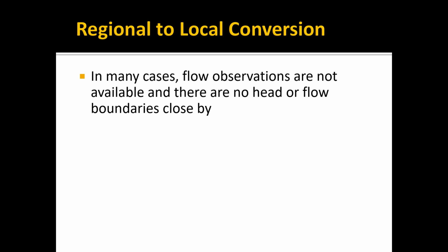And by the way, when I started this example, if we put a head boundary condition based on contours, that's not a good practice. You should only use a head or a head-dependent boundary condition where you have an actual body of water, not an observed contour, if we can get away with it, with an exception, which I'll describe here in a minute.